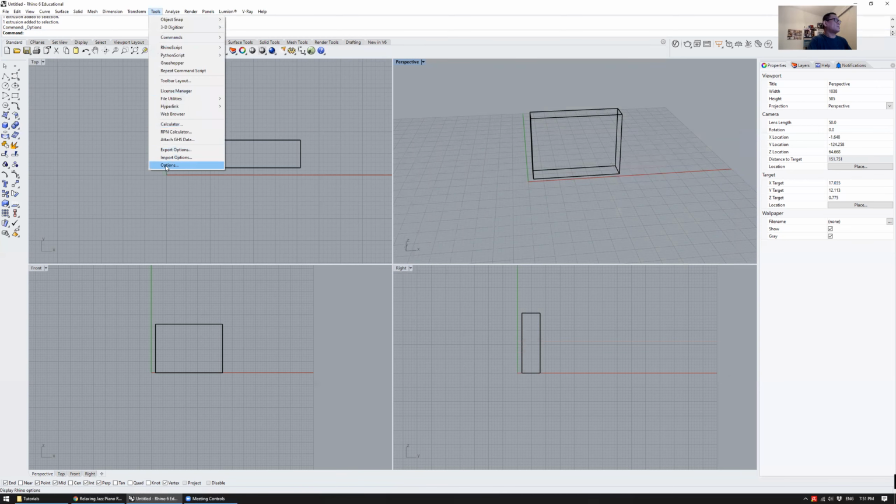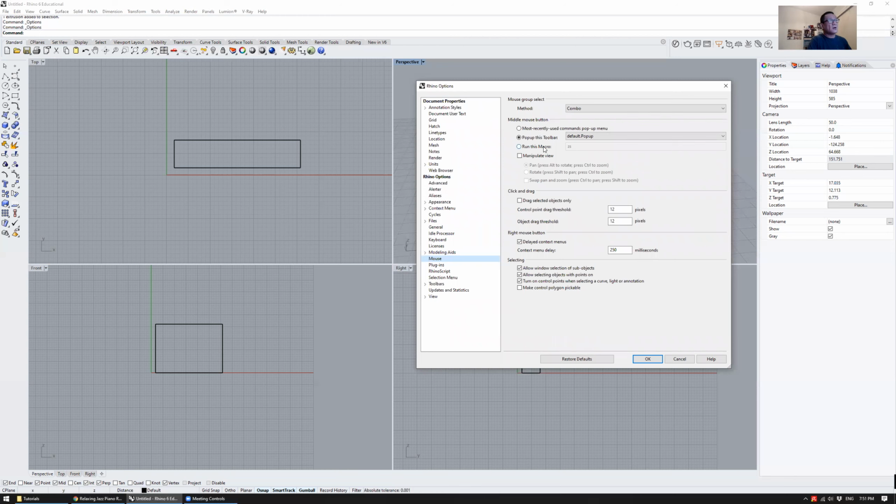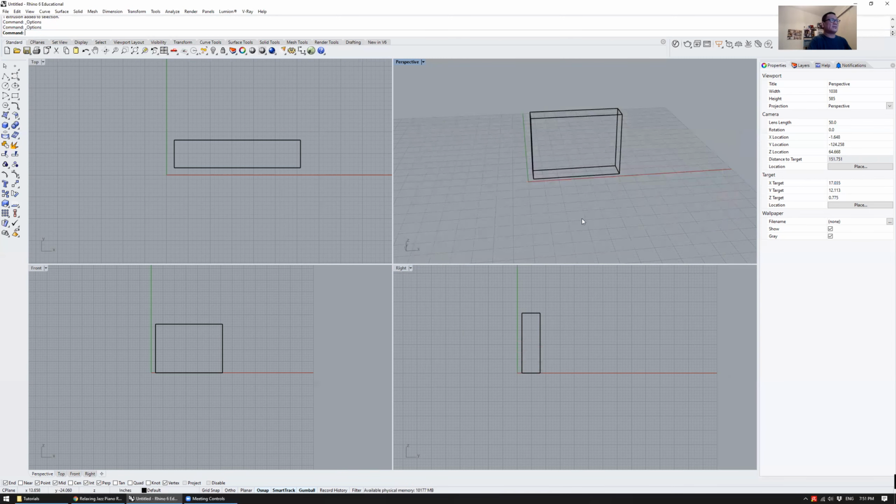So again, go to tools, options, mouse. Click on this, run this macro, and change this to ZS like I have. Just type ZS into here and say OK. What that does is, and I will make another box somewhere else.